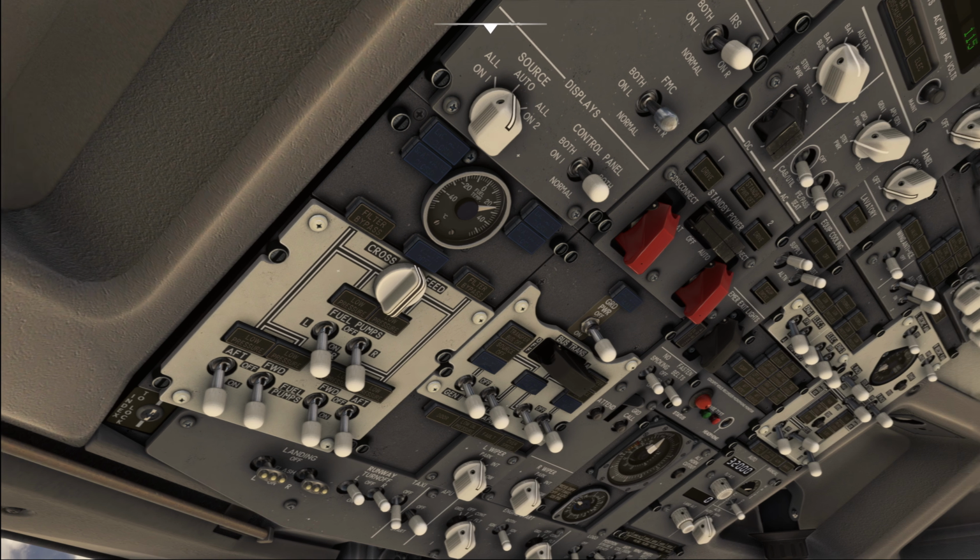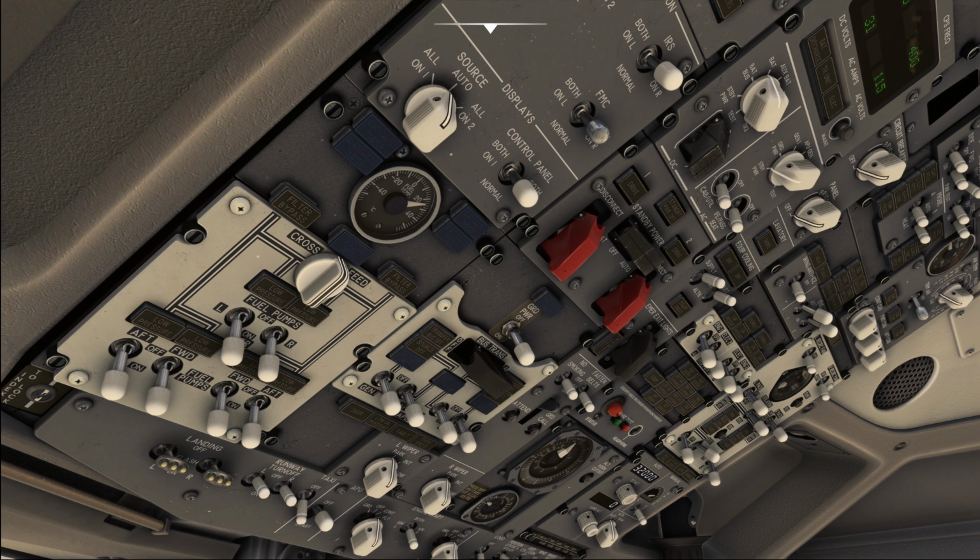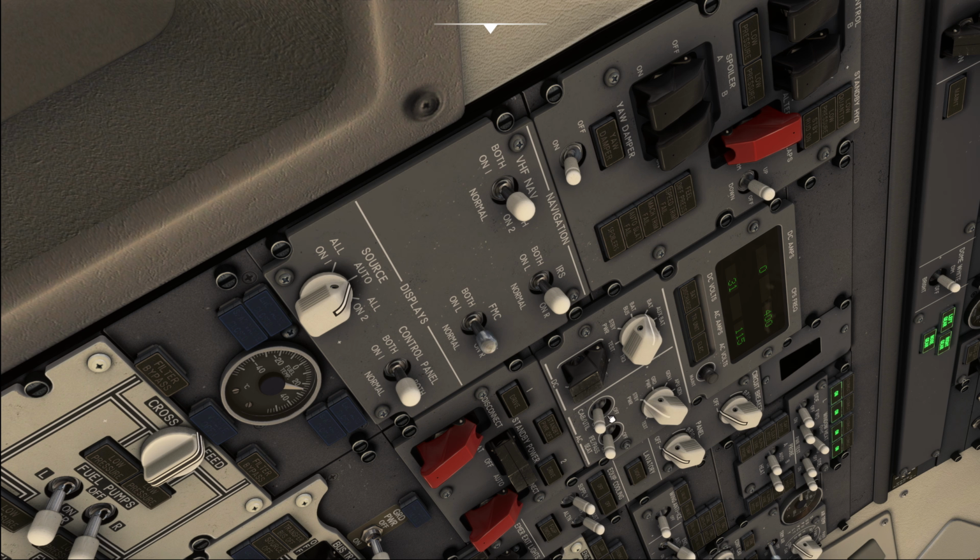Due to cooling requirements of the IDG unit, you will be directed by the QRH to turn off the cabin utility, IFE and passenger seat switches up here, in order to aid with the cooling of the IDG by reducing the load. This will cause the cabin lighting to be extinguished, but the passenger reading lights will continue to work. It is envisioned that in the future this system will be redesigned and the requirement will be removed, but it exists at the current moment.